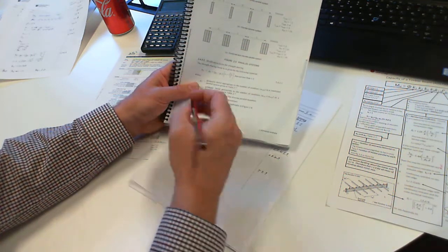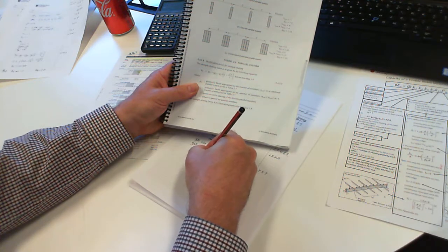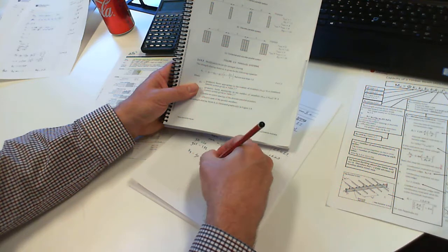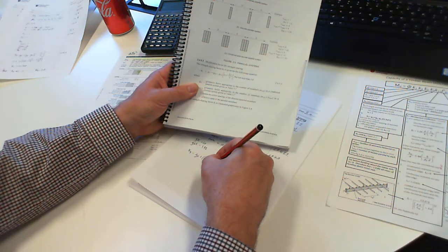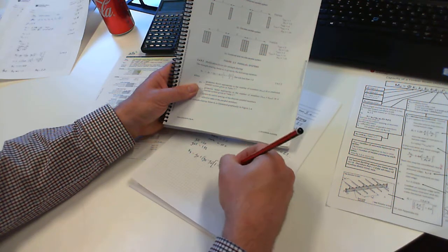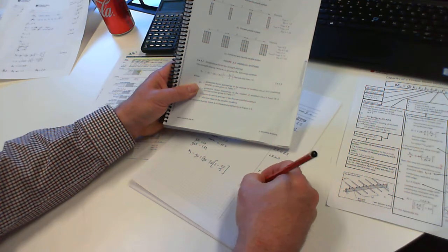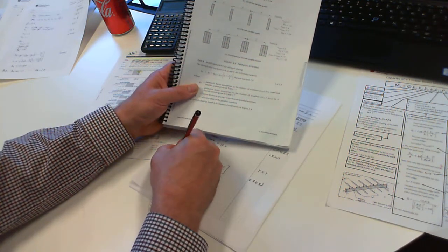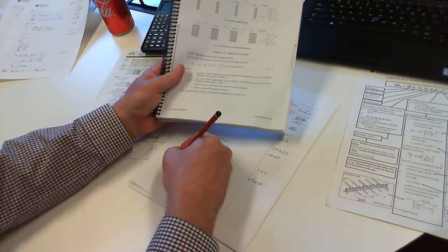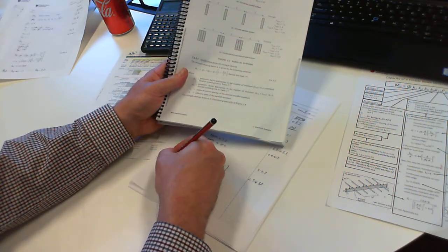K9 equals G31 plus G32 minus G31, all multiplied by 1 minus 2s over L, but not less than 1, and that is clause 2.4.5.3. So we also need S and L. S is the center to center spacing of the discrete parallel members. So that's 900 millimeters. And L is the effective span, which is 6,000 millimeters.